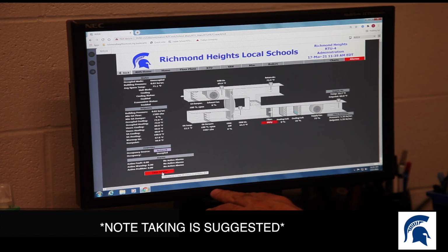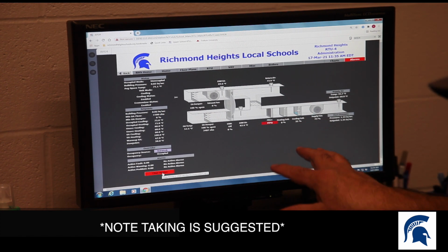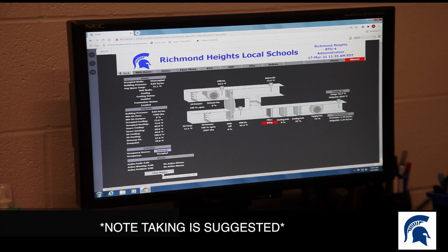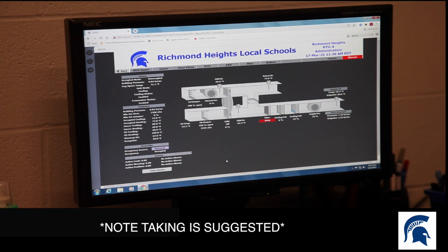So when I clear it, you're going to fix that, so we don't have to go through what we just did. Yeah, you're just going to have to click it and it'll turn red. When you hit that reset button, it takes the value, but then it's just a really quick switch between the reset and then it goes back to not reset. Right, so it doesn't have to stay maintained for a super long amount of time. So that's saying that the rooftop still thinks that the filter is dirty, whether it's actually clean or not.